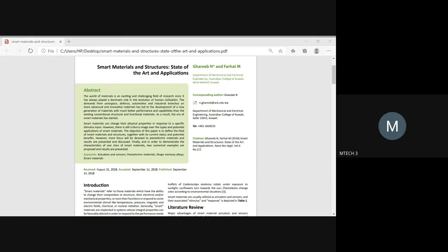Okay. But to make this an actively smart structure, you should have some device which has to sense what's happening in that structure, right? So you need a sensory system, a sensory node, and that sensory node will integrate with n number of sensors. You need more sensors depending upon how many devices you have within the structure. So it has to sense the data from each individual device, and all the data segregated by these sensors will be connected by the sensor node.